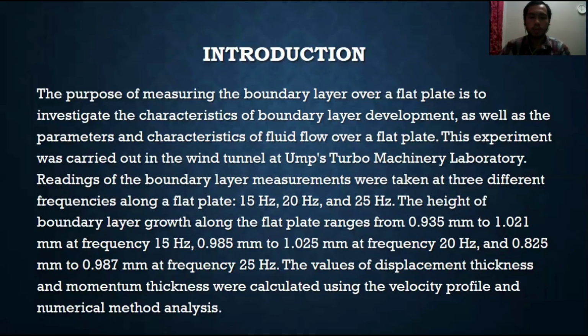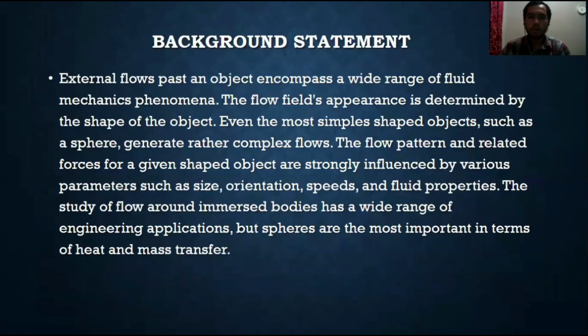The height of the boundary layer grows along the flat plate, ranging from 0.935 mm to 1.021 mm at the frequency 15 Hz, 0.985 mm to 1.025 mm at the frequency 20 Hz, and 0.825 mm to 0.987 mm at the frequency 25 Hz. The values of the displacement thickness and momentum thickness were calculated using the velocity profile and numerical method analysis. So we go to the next part, which is the background statement.